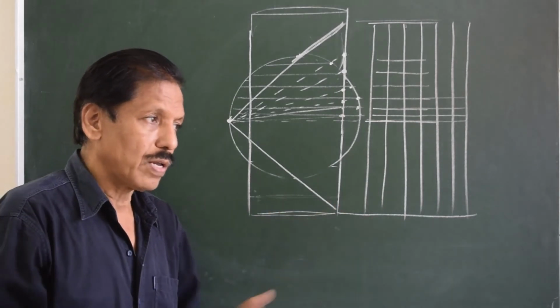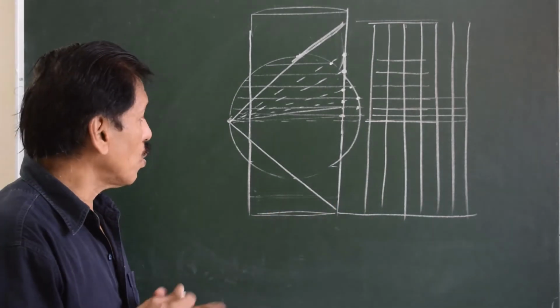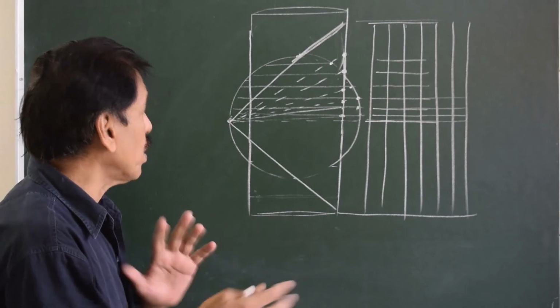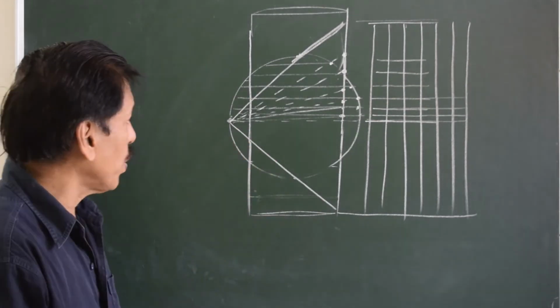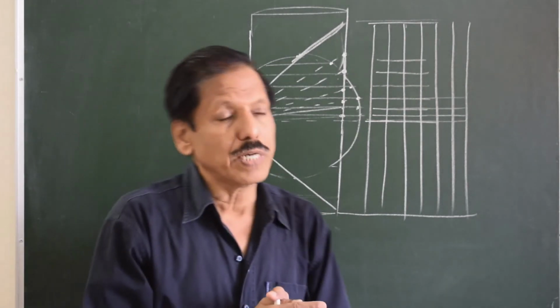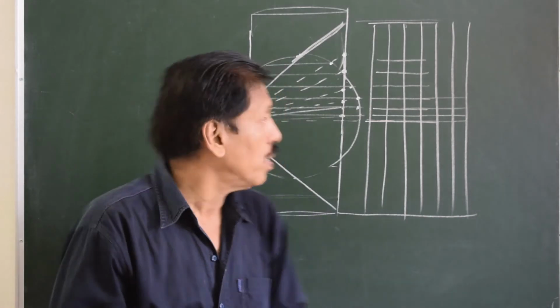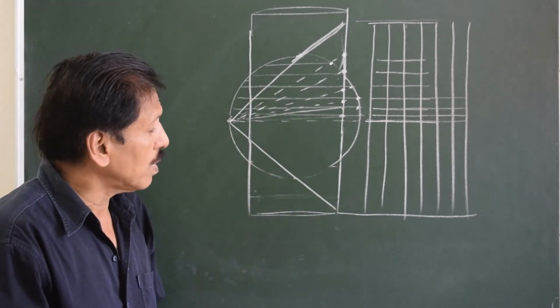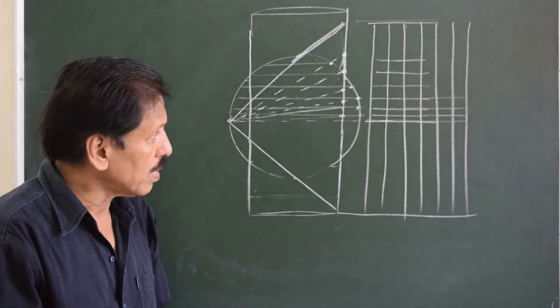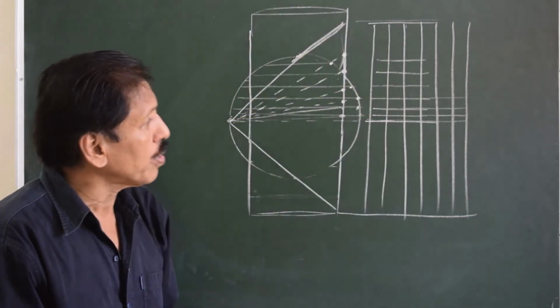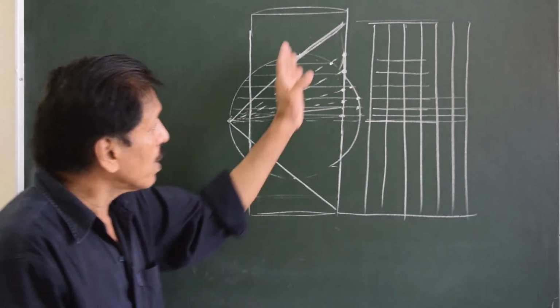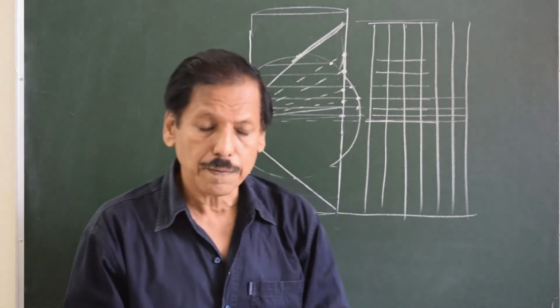You can actually represent the entire globe in this. The beauty of this projection is you have chosen a point outside the cylinder, and you are able to project and view the entire globe on the inner concave of the cylinder. The appearance would be something like this: increasing distance of parallels of latitude as you go towards the pole, and the pole is represented by a straight line.